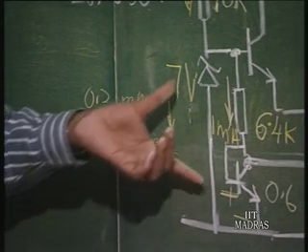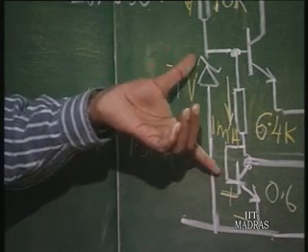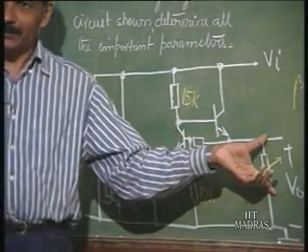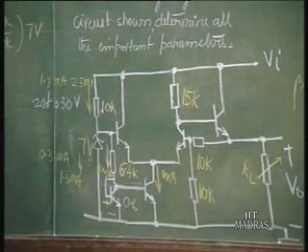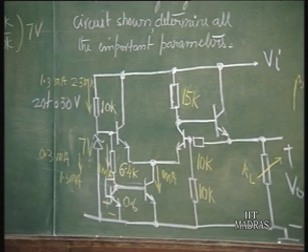It will not be constant at 7 volts. That change in Zener voltage is what is going to appear at the output as 2 times that. So, let us say at 0.3 milliamperes it is some value 7 volts, and at 1.3 milliamperes it is 7.1 volt, okay, higher. Then correspondingly output will be changing from 14 to 14.2 volts.